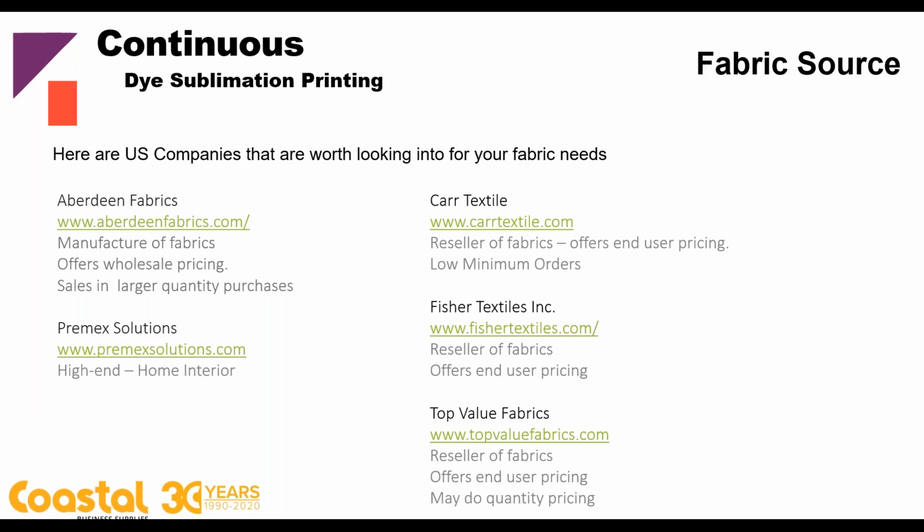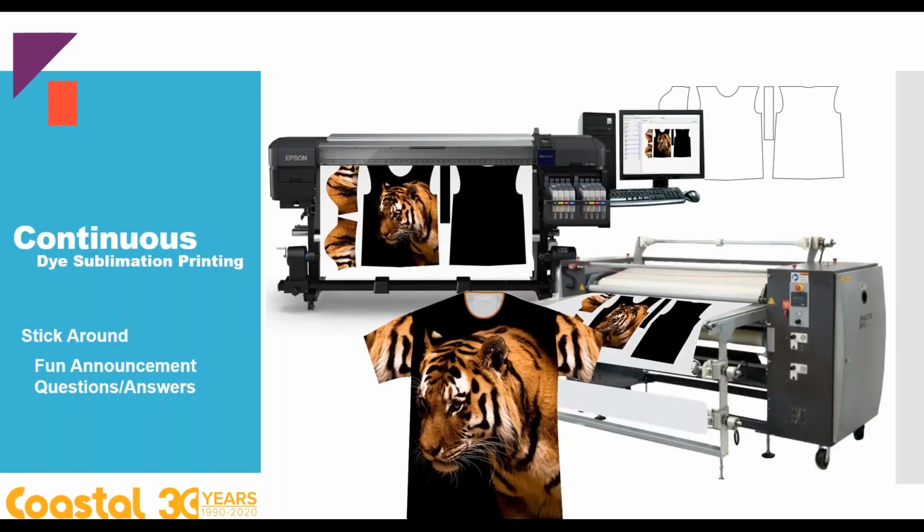So we've done a full circle here, where now we have the solution for the patterns. You would do your designing, bring those patterns into Adobe Illustrator, CorelDRAW, or whichever program you're working with, and lay out your design inside those patterns. We'll print them off using one of our Dye-Sublimation printer solutions, and then the Rotary press to get the final product. And that is how you do apparel or any other type of production for continuous Dye-Sublimation printing.